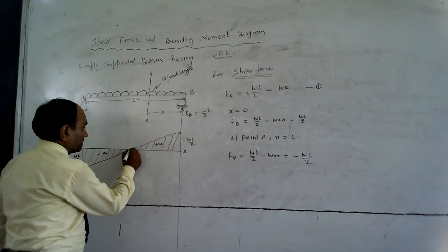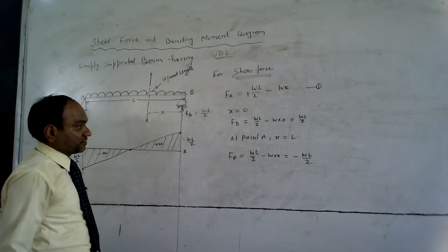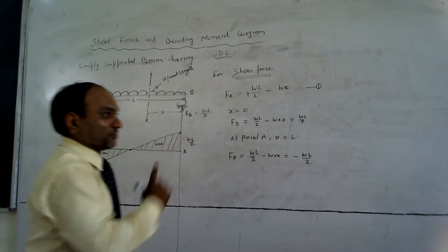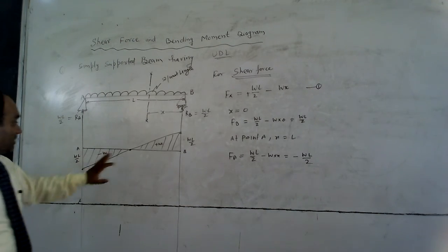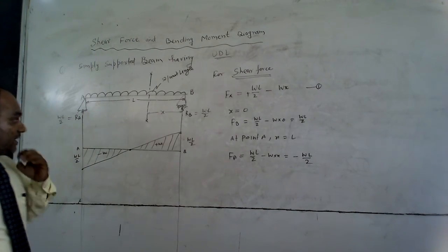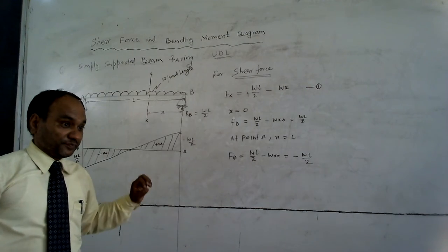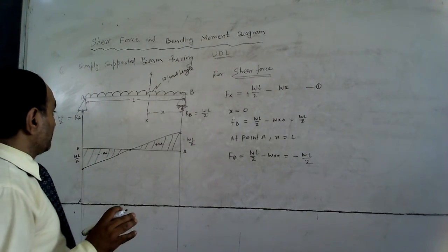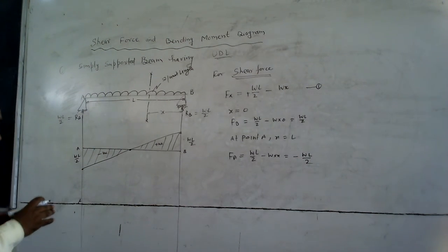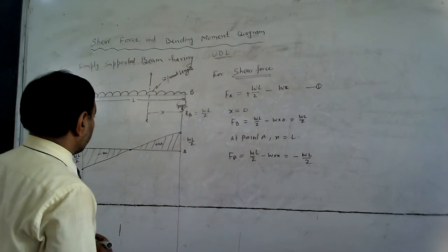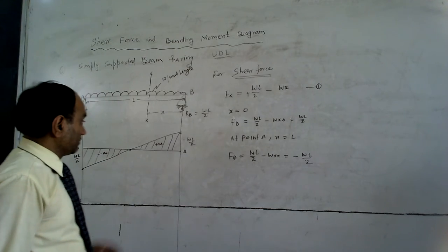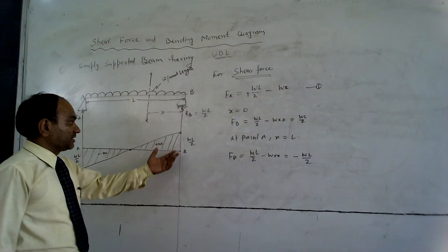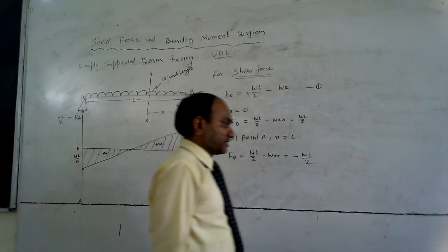At the midpoint, the shear force is 0. You have to remember this figure, and we can utilize these values when we are designing the beam. At that point, we calculate the shear force at different points by utilizing this figure.